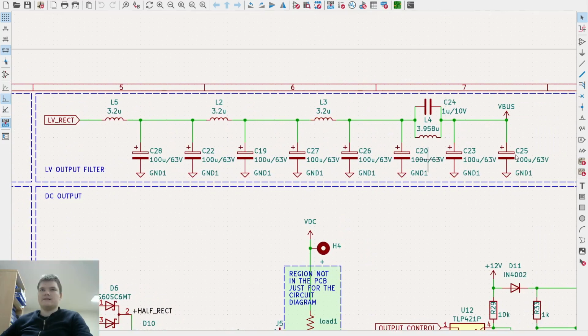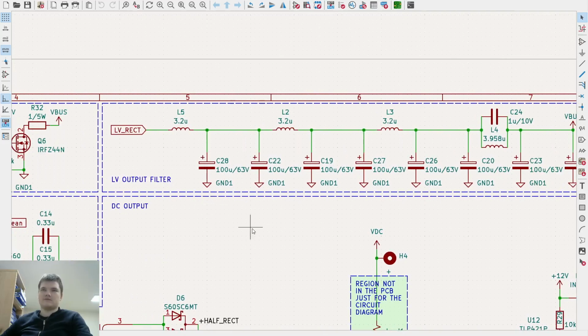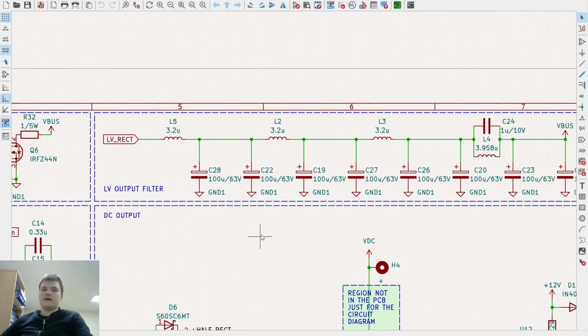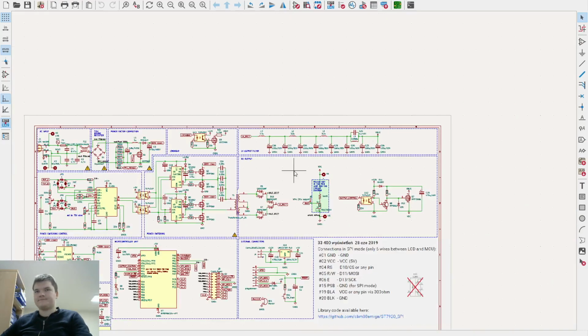If the new voltage is set to a lower level, it basically discharges these capacitors to a new level. I think this also should work if suddenly the constant current mode is entered, and not the constant voltage, because constant current makes the voltage drop.